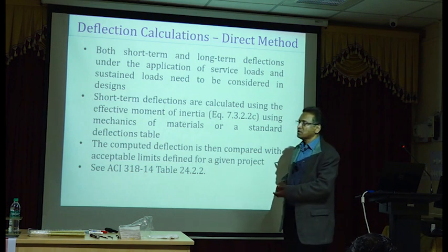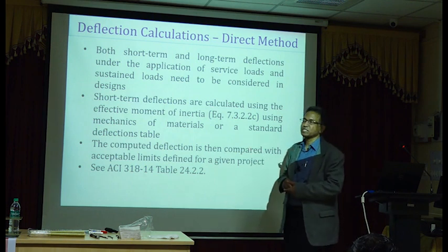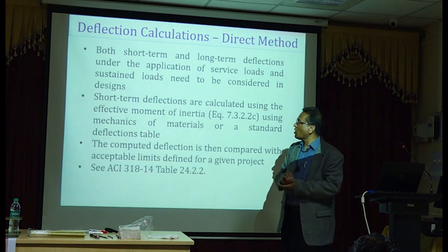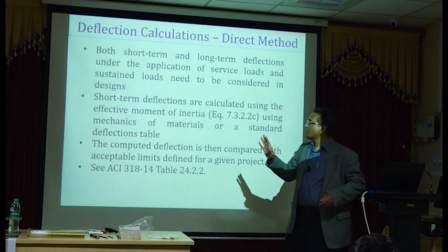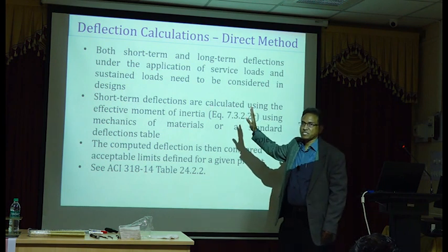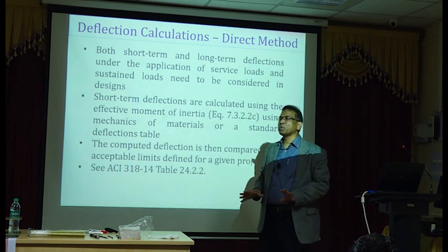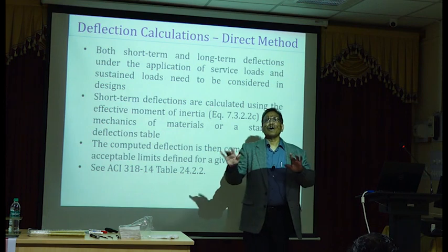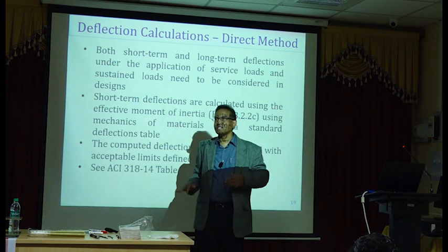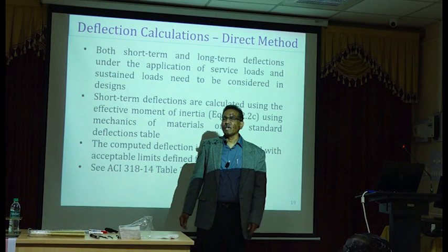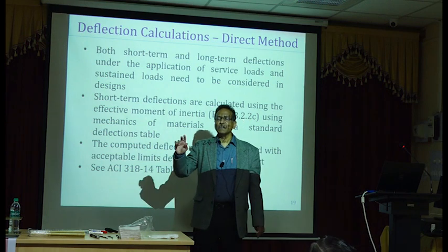Many times students, not experienced professors like you all, make a mistake in terms of loads. If you are using a fancy program, you plug in all the load factors and then you come back and say, oh, my deflections are not working. They're not working because you are using factored loads.